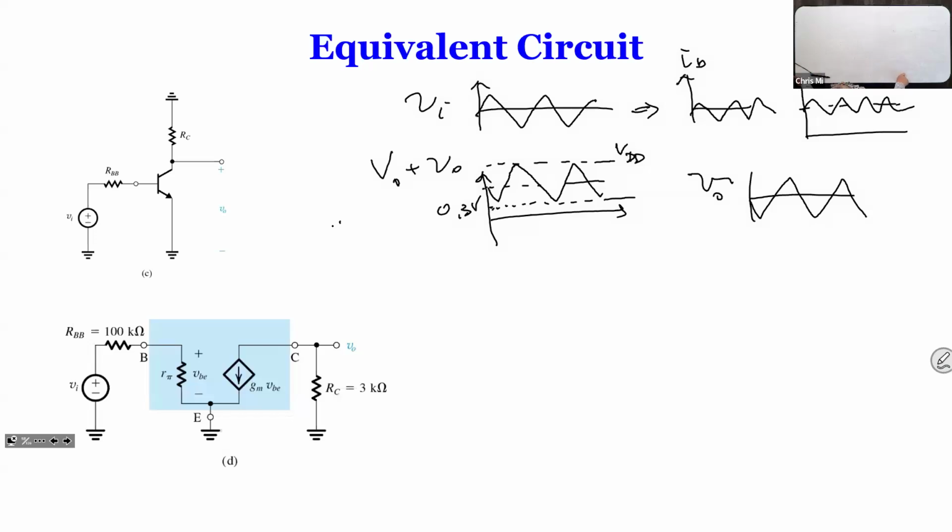So if my waveform was clipping, what would be the thing I would adjust to fix it? Well, if you clip on one side, you can adjust your biasing point to move it up or down. Let's say it was too big for both. For too big for both, make it smaller. Would I just change GM or something?